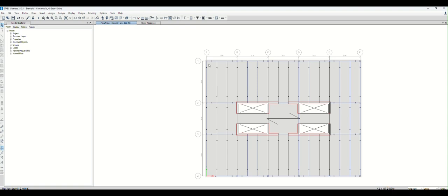The building is rectangular, so the wind pressure on Y-axis is bigger because the tributary width is bigger than X, right? Also, your core wall, the concrete tube, when blowing in Y direction, is our core wall tube's weak axis, which shows less lateral stiffness. So that's why we end up with big deflections.